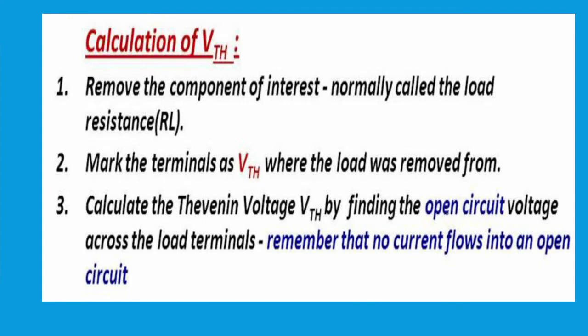Now, the first step is to calculate the VThevenin. So how do we calculate VThevenin? Remove the component of interest, normally called the load resistance RL. Mark the terminals as VTH where the load was removed from. Then calculate the Thevenin's equivalent VThevenin by finding the open circuit voltage across the load terminals. Now for the given circuit, I'll try to redraw the circuit we are discussing here.